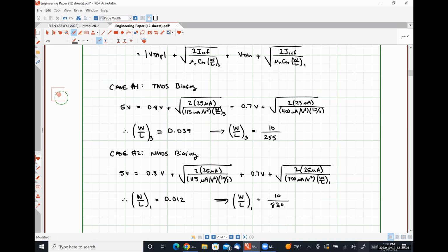All right, so this particular configuration eliminates or mitigates, I guess would be a better term, since mobility is definitely temperature dependent. It mitigates the temperature dependence issues that using an actual resistor contributes. But there is still dependence on the power supply voltage, right? Because this equation is literally VDD is equal to this other stuff.